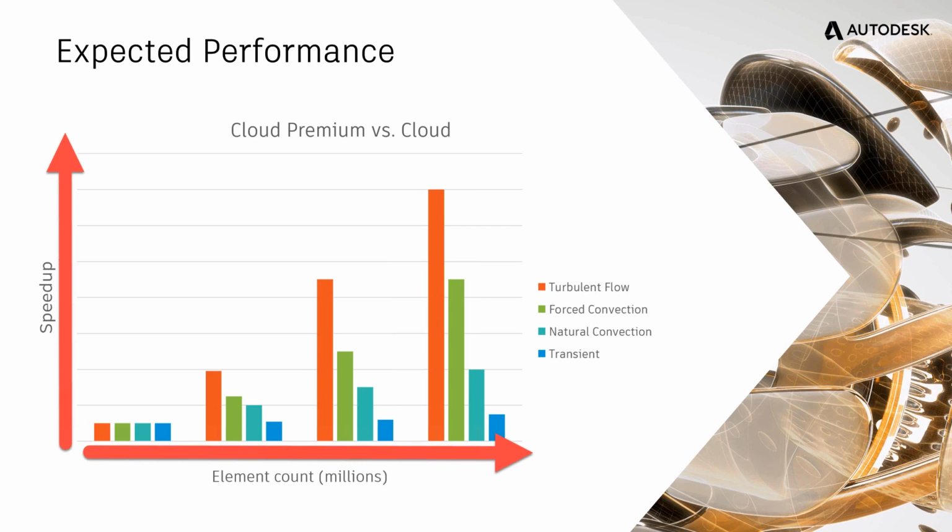You get a very, very similar answer from the different solver. But I would run turbulent flow, forced convection, conjugate heat transfer, steady state with constant fluid properties. That I would probably run. The natural convection and the transient, I might run one as a test case just to see, but I wouldn't count on those to have great performance gains right off the bat. But again, the solution has great promise for those problems as well, and it's going to progress. And as we see huge gains, we'll continually update you guys.